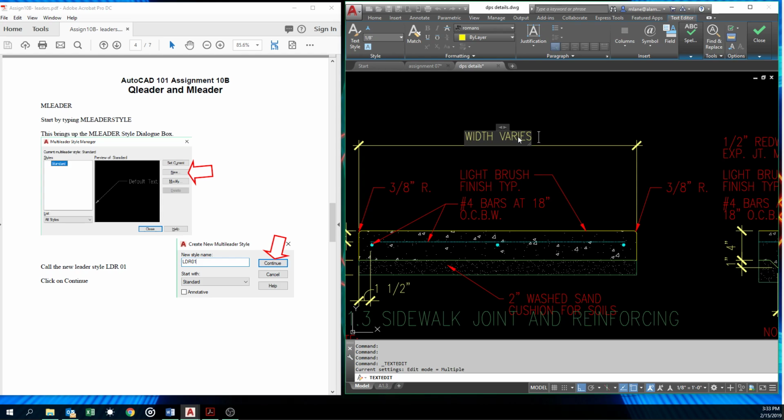And if I wanted to say plus or minus and then put the real number, if I hit a percent P, that'll give me a plus minus symbol, space, and then put a less than and a greater than, and when you do that, it puts the real dimension. I know this is a lot more information. I'll do a whole thing over these.